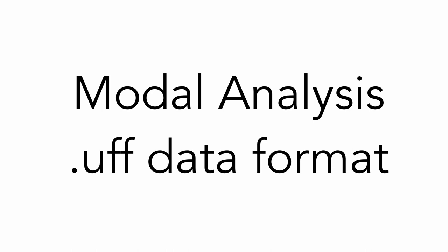It is designed for laboratory use, but VA5 is small and easily portable. You can measure all required FRF in all points and export them in UFF format. And then in laboratory you just import these files to your modal analysis software.